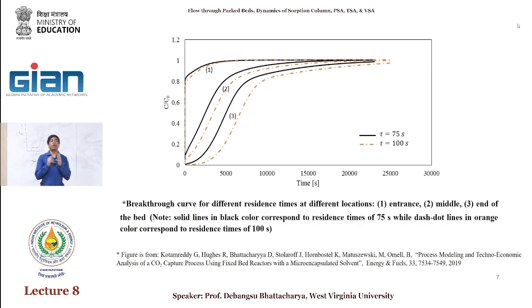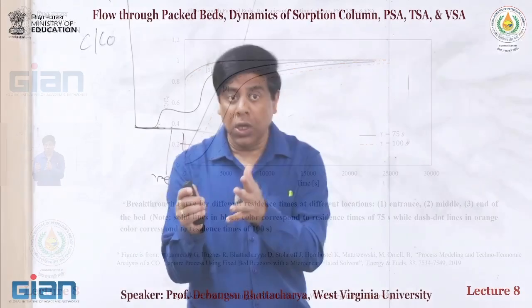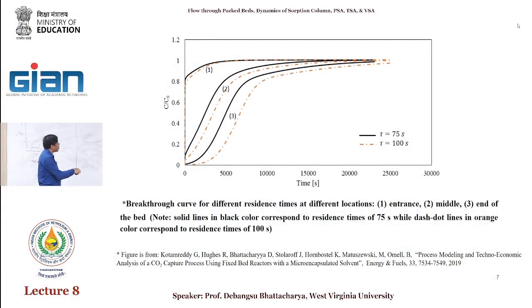This tells you how the bed should be sized, because if my bed size was for the residence time here and my breakthrough was somewhere here, I have almost instantaneously broken through. So this gives you what the bed length should be. This is how you can simulate a very long bed, look into it, and then chop it and say, okay, this is where my bed size should be. You can always do a longer bed, and after you simulate these breakthrough curves, that will help you design the bed.